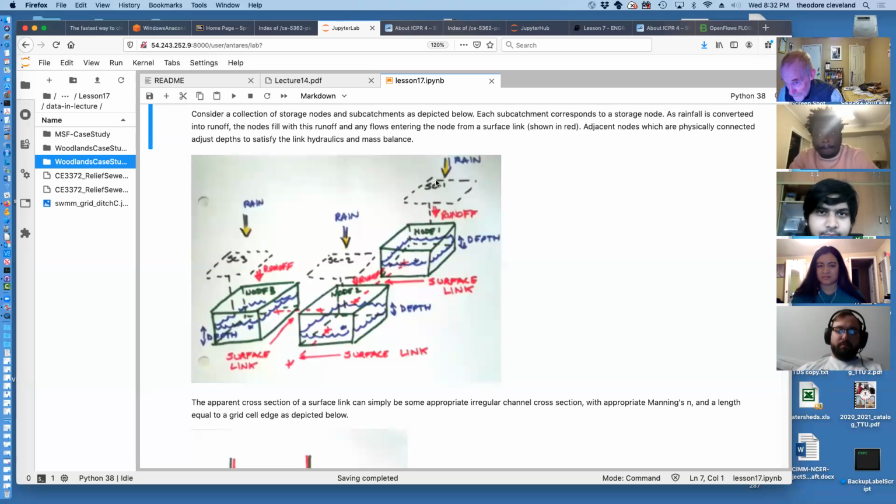So this dashed rectangle either implements, in the case of SWMM, curve number, Horton, or Green-Ampt, or variations thereof. And although it's often criticized as a limitation of the program because it doesn't do every whiz-bang model that there is, an ingenious analyst can use the three models within it, and in many cases simulate not any, but almost any of the ones in the literature.